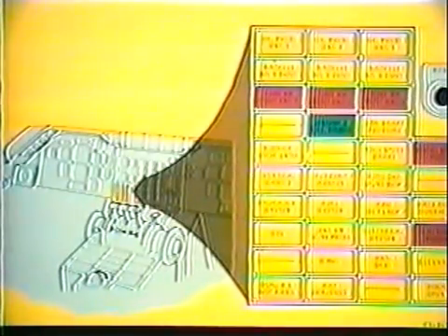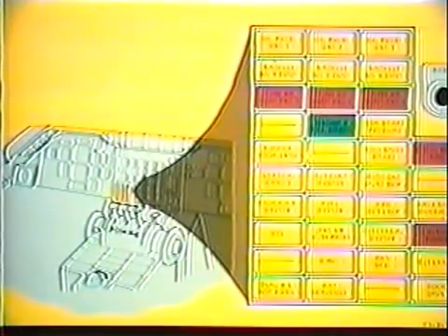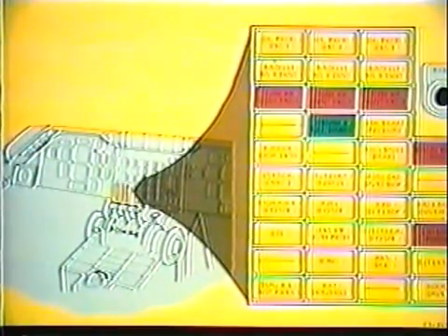An exception to this is the green Engine 2 fail-armed light. It is green because it is a normal condition not requiring crew action. It does not flash and will not reset.